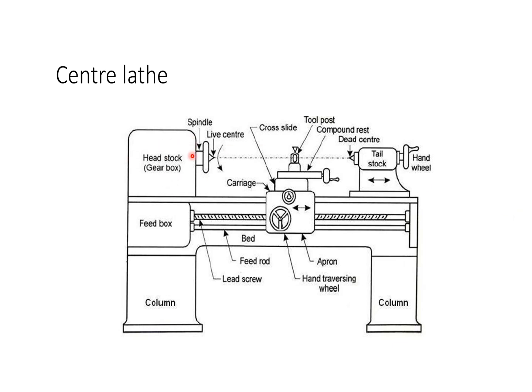Next, this is the headstock. So it holds the spindle, and through that the power and rotation are transmitted to the job at different speeds. Various work holding attachments such as three-jaw chuck, collets, and centers can be held in the spindle. The spindle is driven by an electric motor through a system of belt drives and gear trains. Spindle rotational speed is controlled by varying the geometry of the drive train.